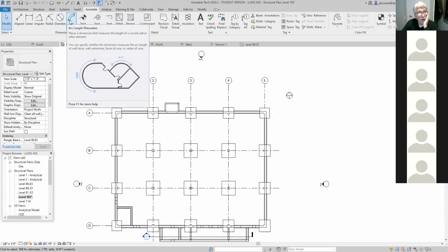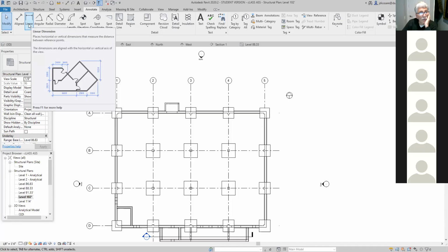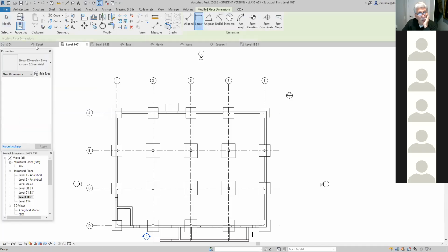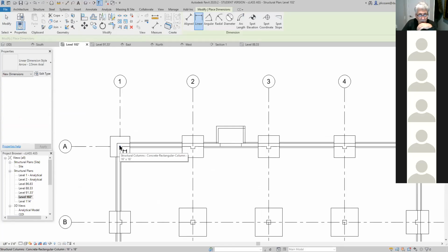Now, I know that in AutoCAD, you can use the command linear to do a linear dimension. The problem with Revit is that when I use linear, keep this in mind. See here, there's a drag point, so I can go to that point. Here there's a drag point, so I can go to that point. So with linear, if I have the two drag points, I can literally use that command. So I'm going to just put it about here for now.